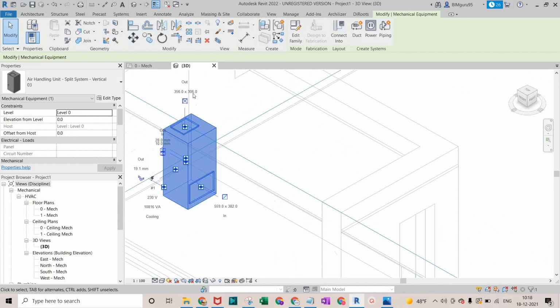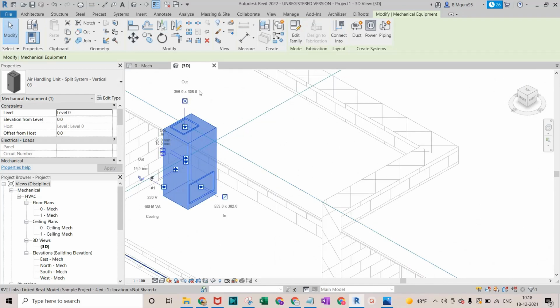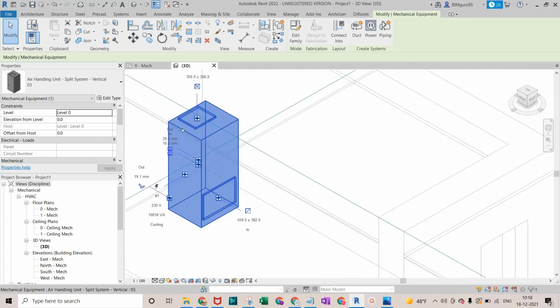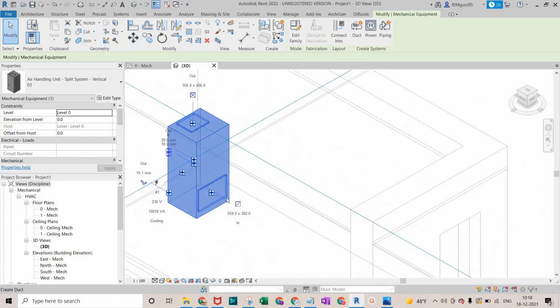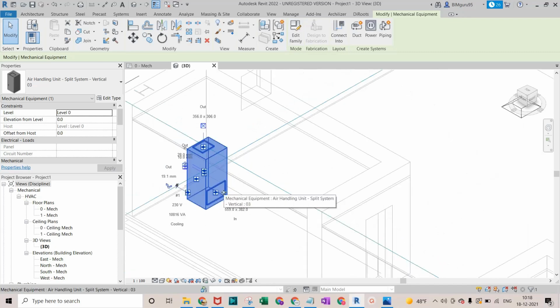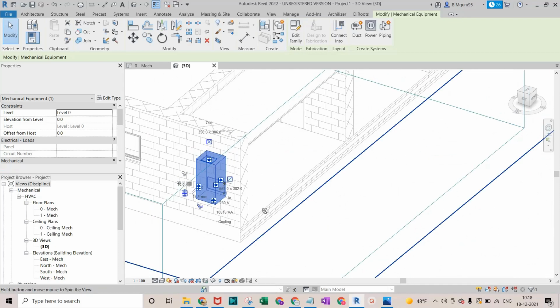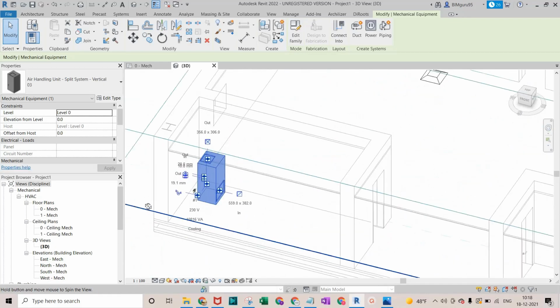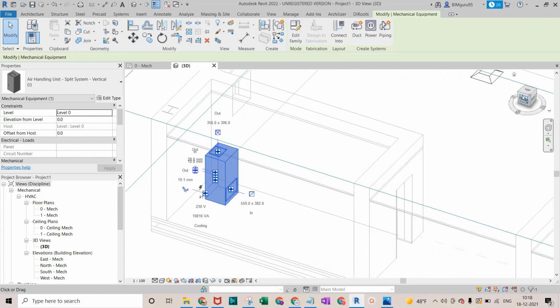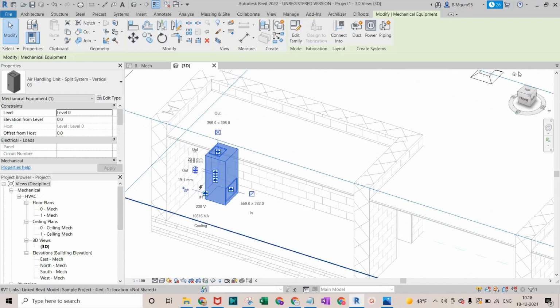This is outside air. It means the fresh air part. This is the return, but I guess we should go with this only because this is for the return that I already discussed with you. Instead of that, I do not think they have provided any. Okay, no issues. In some of the AHUs, we only have two ports, like return and supply. And in some cases, we have three ports: return, supply, and the fresh air as well. So if it is not that, that'll be fine.